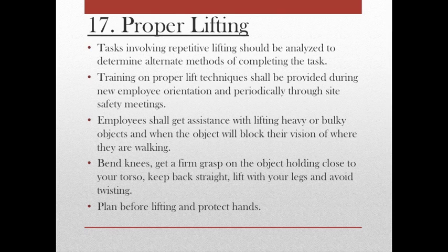Plan before lifting. Consider weight, size, shape, path of travel, and set-down location. Get help if necessary. Protect hands and fingers from rough edges, sharp corners, and metal straps. Keep hands and fingers out of pinch points between the load and other objects.